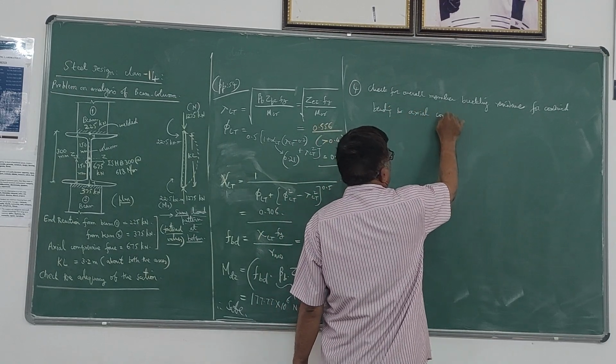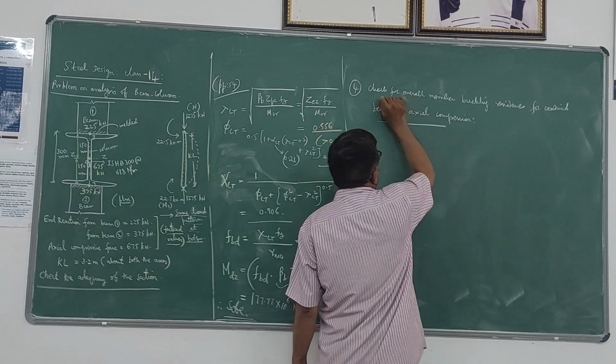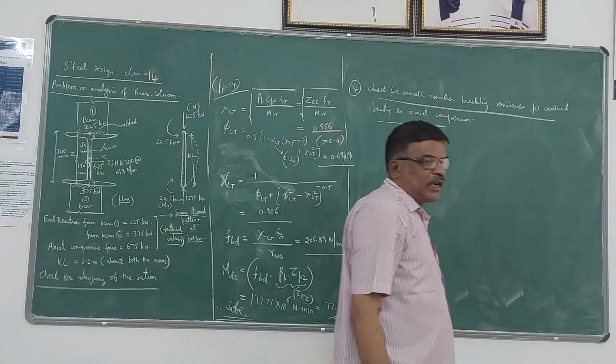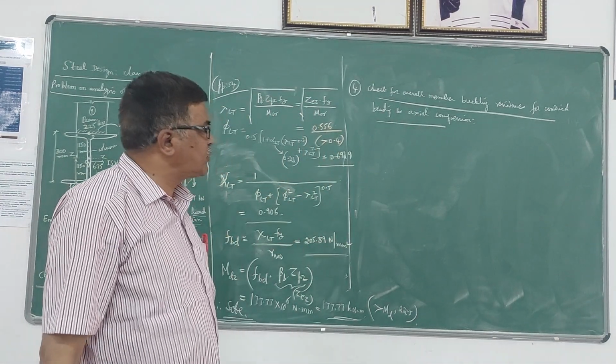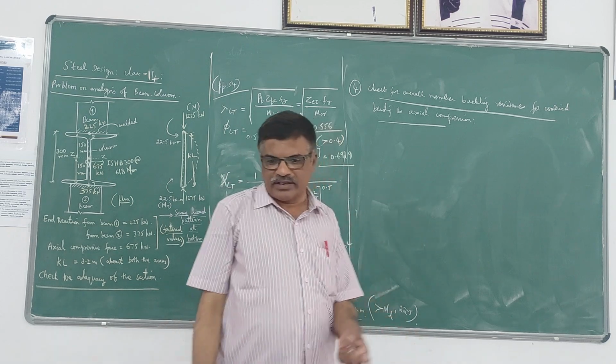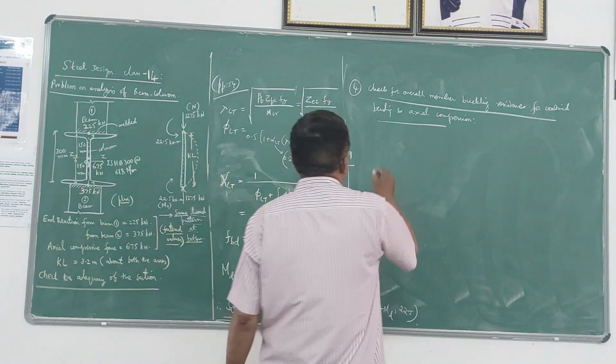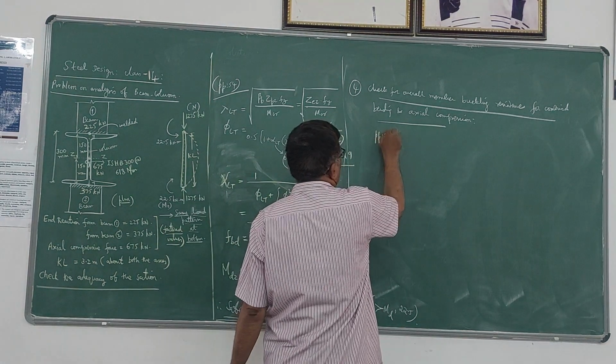What we have done so far is treat the beam column as a column and a beam separately. We have checked the compressive strength as well as the bending strength separately. Now we are combining both effects as a beam column. For that, refer to the equations on page number 71 of the code.